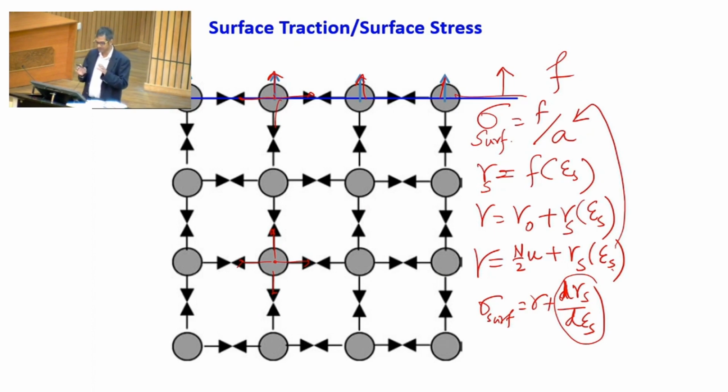So, you understand that surface energy is first and foremost an important thing in a solid nanomaterial. Surface energy is critically going to depend on this surface stress. So, that means surface energy has two components. One is the bond breaking, that is given by u by 2 per mole, the other one is because of stretching, correct. It is very difficult to estimate this. There is no experimental procedure available in the world today which can allow us to estimate this gamma s.